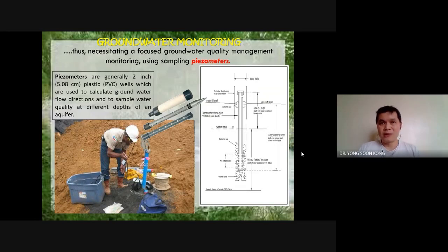So this groundwater will flow downwards with gravity, and also because of the permeability of some soil. Now you know that clay doesn't allow water to seep in. So when this groundwater flow encounters a layer of clay, it's going to flow along the surface of this clay, horizontally.